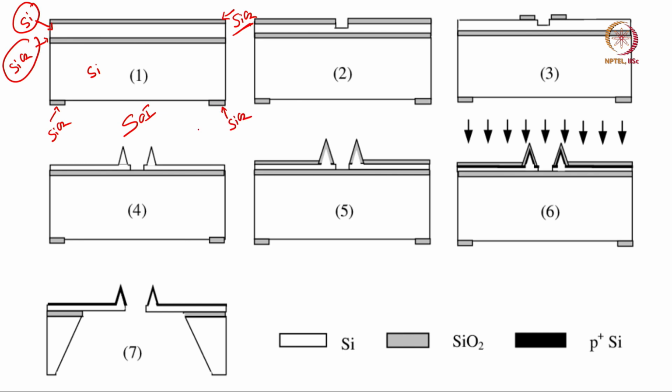then you perform lithography so that the silicon dioxide from the back is etched, as you can see from this particular image. After that, you do the etching so that you can create a window. You can see here on the front side you have created a window, and then you have etched the silicon. After that, you can pattern the silicon dioxide as shown here. After that, you sharpen this by etching the silicon completely, and there is an etch stop here, because in silicon